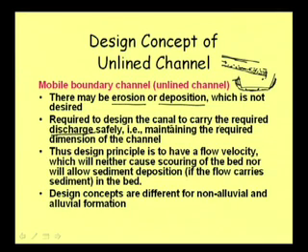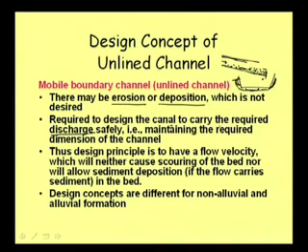So, this discharge safely. By safely, what do we mean? Maintaining the required dimension of the channel, which means it should not get eroded, neither should there be deposition. Thus the design principle is to have a flow velocity which will neither cause scouring, that is erosion of the bed, nor allow sediment deposition in the bed. So, this is the design criteria.